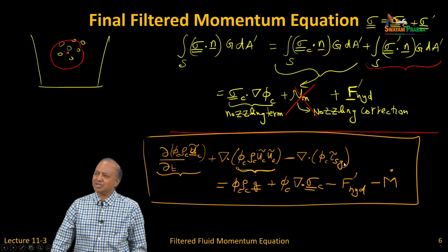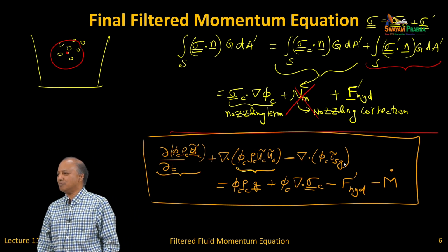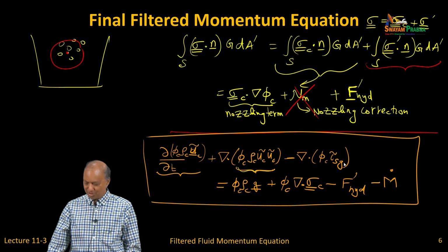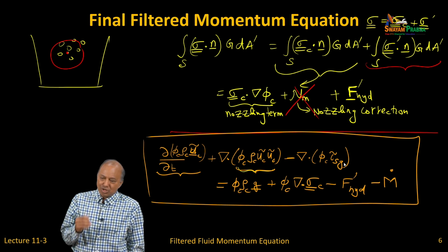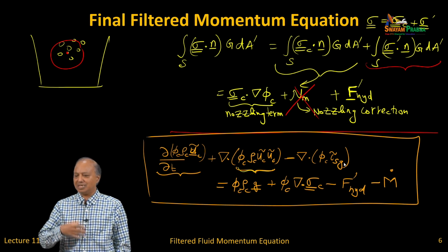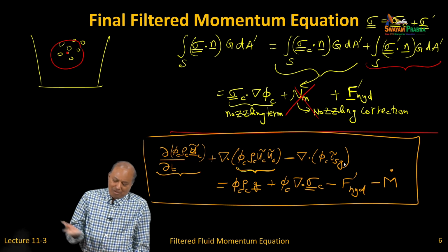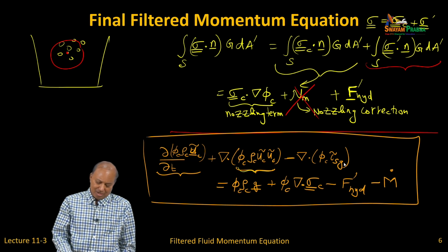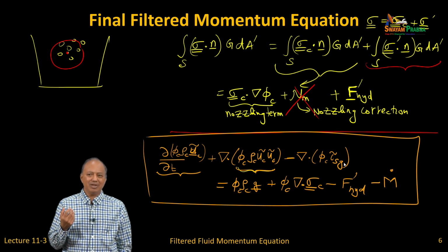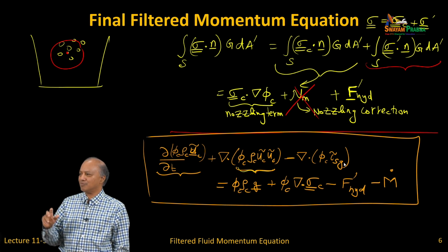The only thing I will say is that this turbulence may not be only classical turbulence, but may include pseudo turbulence. Okay. So, it is turbulence that is not resolved, that is smaller than your grid, the same as in a single-phase problem, basically Reynolds stress or LES subgrid closure, but you may want to think that the turbulence you close is maybe different because there is some pseudo turbulence in there.